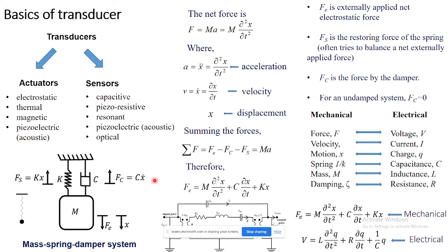Eventually, we have this complete embedded system where the sensor and electronics are all integrated and sitting on top of a PCB, and we have this microcontroller. Let's say we are measuring a physical quantity, and the output is the digital reading. The capacitance coming from the sensor changes and is converted into an equivalent voltage. Those analog values are converted with an A to D converter, which could be an inbuilt part of the microcontroller or outside of it. And we have digital codes that are correlated with the input quantity.